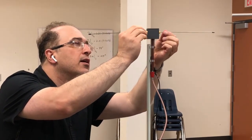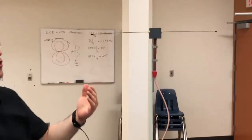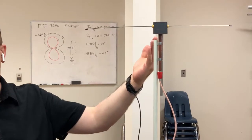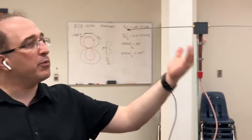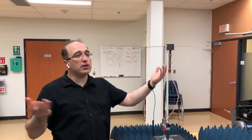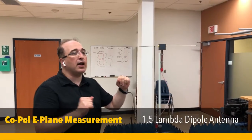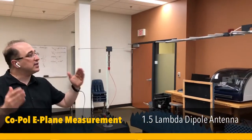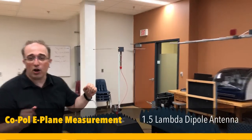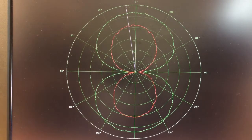Now, as we change the length of the dipole antenna to 3 lambda divided by 2, we have a new current distribution on the arms of the dipole. And because of the new current distribution, we're going to get a new radiation pattern that we're going to study. Again, as you know, this structure that we mounted the antenna and the transmitting antenna on is for measurement of the E-plane cut. So now we want to collect the E-plane cut of the 3 lambda divided by 2, 1.5 lambda dipole antenna.